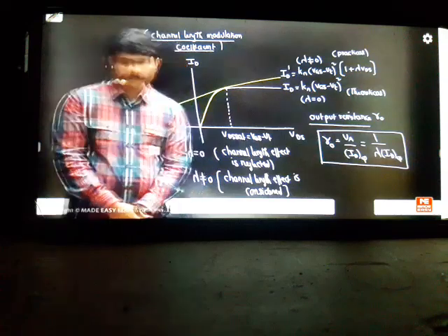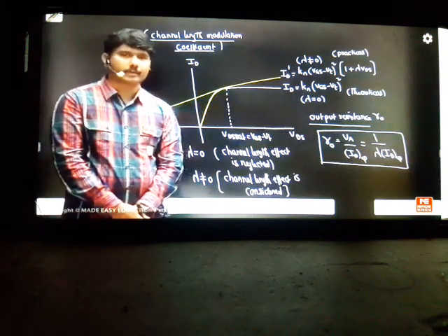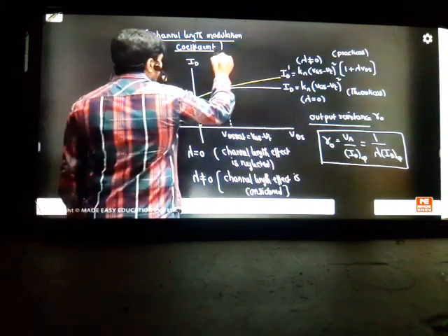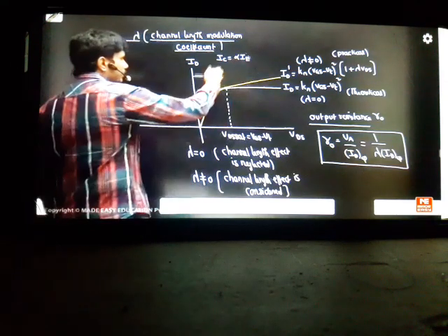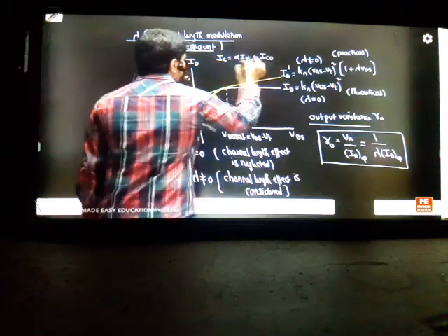Rahman, you are asking that when BC is reverse biased, then IC will be 0, you are saying. That is wrong thinking here. Generally in our BJT transistor, our formula is IC equal to 2 currents, not 1 current. One is alpha times IE, which comes from the emitter junction, crossing the depletion region, plus one more current, IC naught. We have 2 currents, my friend.